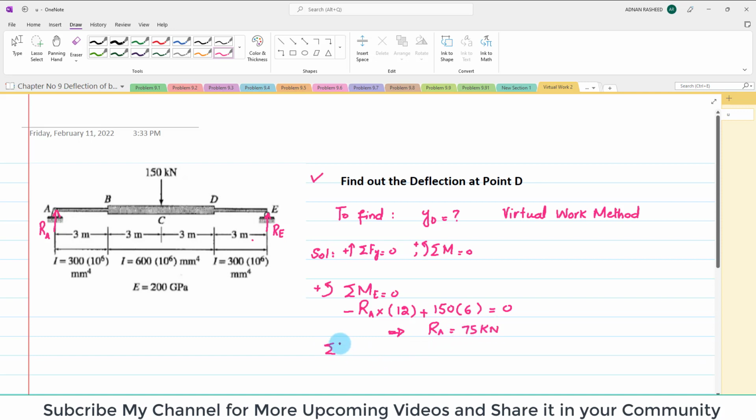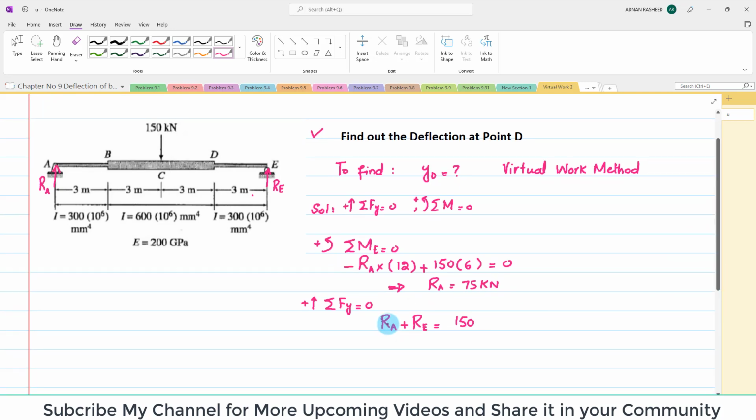Now by using the other equation, the sum of all forces along the y direction must be equal to 0, with upward positive. You can see RA plus RE is equal to 150 kilonewton. If you have RA, you can put in the value of RA. So RE will again be equal to 75 kilonewton. Now these are the reaction forces at points A and E.